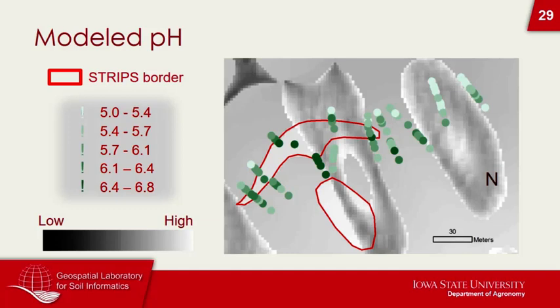So when we refer to northing, it is part of aspect. So aspect asks you which direction is the surface facing? Is it facing north? Is it facing south? Is it facing west? Is it facing east? The way that it's normally measured numerically is from 0 to 360. Measuring on 0 to 360 makes a small complication for calculations, as 0 is 360. So a high value is the lowest value. So we separated those two. So the degree of how north-facing you were was a useful way to divide the data. So it was related to the aspect. Yes. Okay, that helps a lot. Thank you.